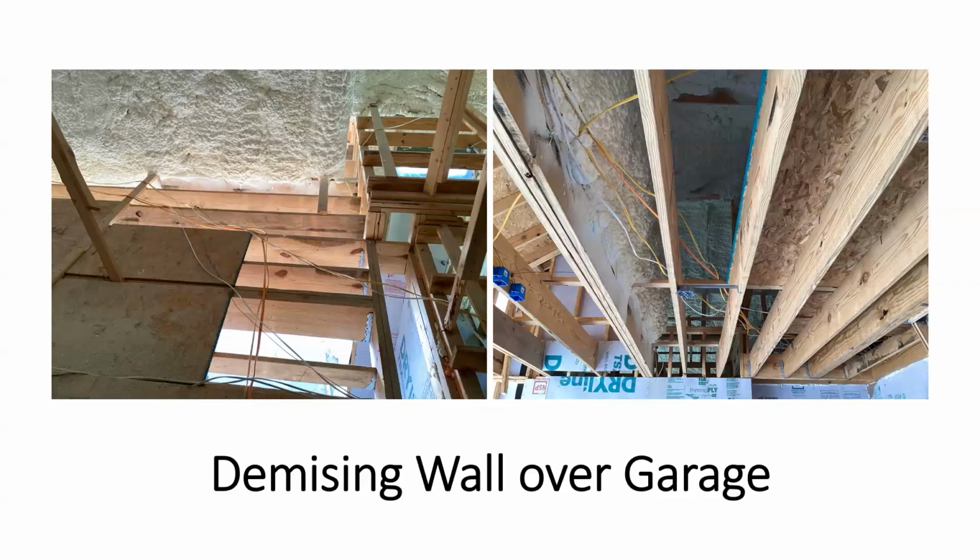This is what I talked about earlier about misalignment when you're looking at foam, what we saw looking over the knee wall and saying this isn't correct. This is me standing in the garage. I'm in the attic above the garage in a foamed encapsulated house. So they've moved the demising wall or curtain wall further out over the garage. However, there's a huge portion of the floor over the garage that isn't being insulated. And if that's now considered a conditioned space, it's a misalignment of the thermal envelope.